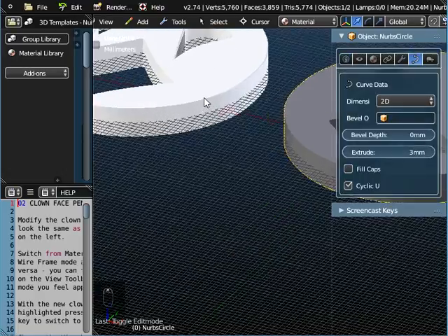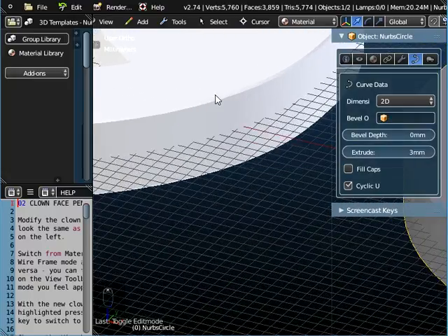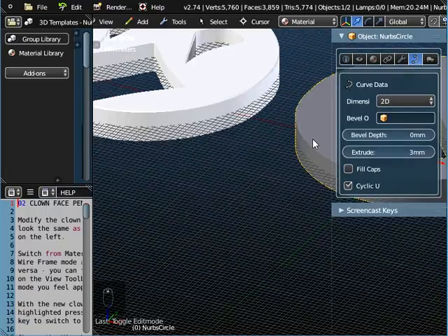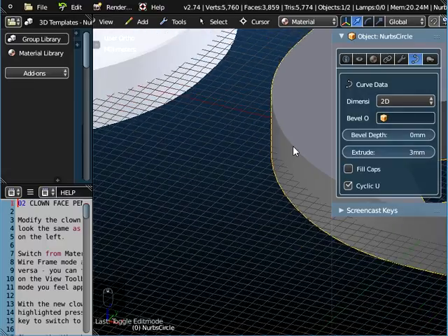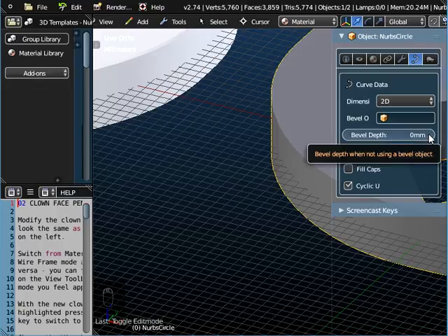Now if we zoom in on this object over here, you'll see that the edge of the object isn't square. What we've done is put a beveled edge. We don't want sharp edges quite often in objects. Well, I say we don't want; you can if you choose to, but we can also smooth off the edge by giving it a bevel, and we do that by changing the bevel depth here.